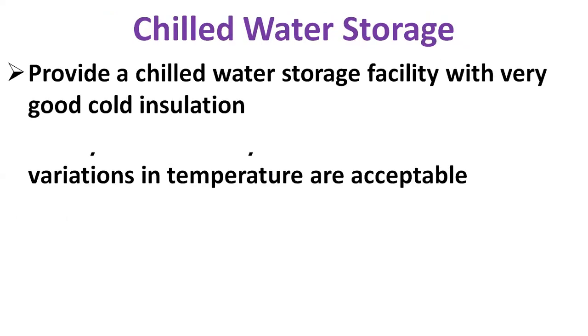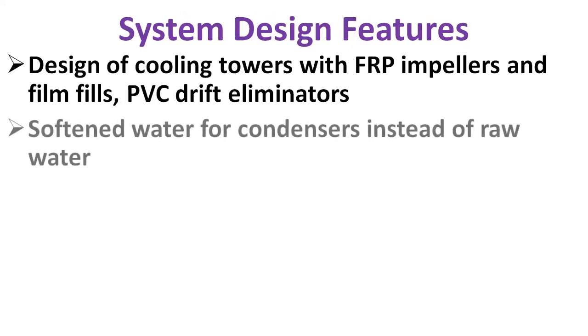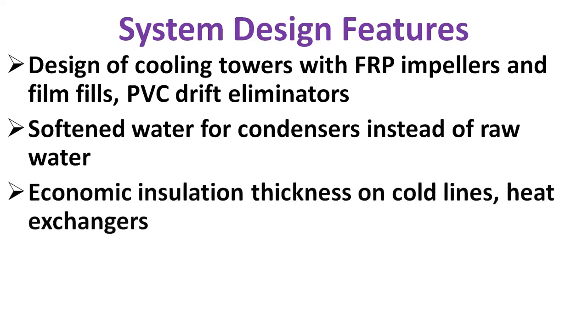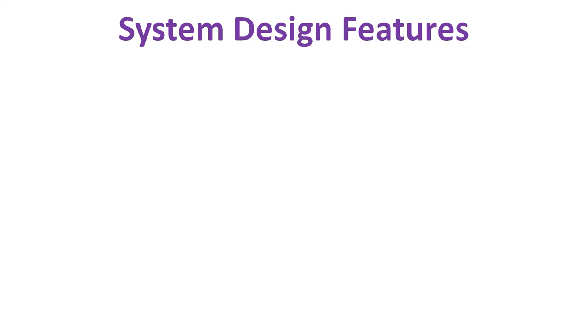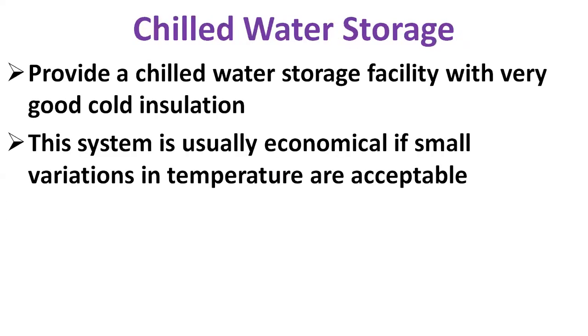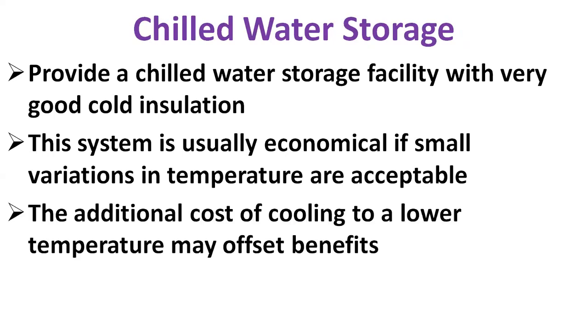Then we have the chilled water storage. Depending on the nature of load, it is economical to provide a chilled water storage facility. Depending on this, the storage facility can be filled to meet the process requirement so that chillers need not be operated inefficiently or continuously. The additional cost of cooling to a lower temperature may offset benefits. The solutions are case specific.